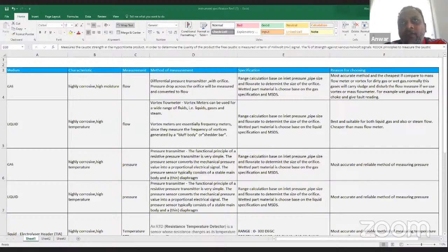You can have level in terms of percentage, how many percent full, 60%, 70%. It can also be indicated. From there, if you know the density of the liquid, you can convert that into the actual mass amount of liquid that you have in the storage tank, like tonnage.